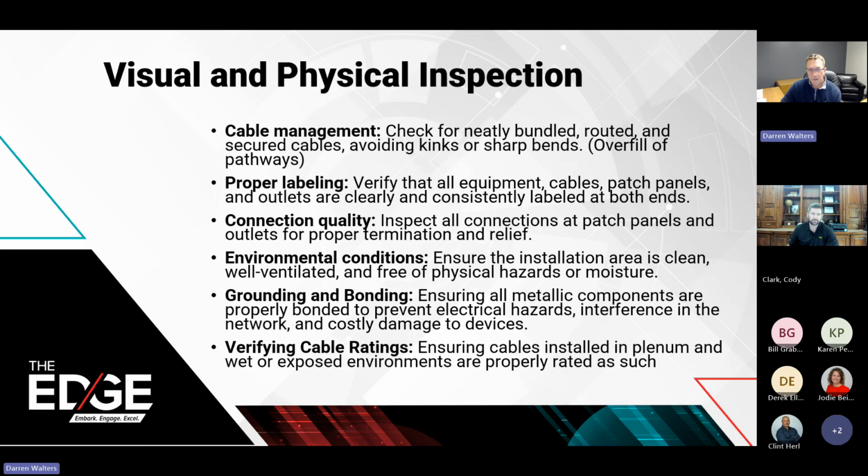Yeah, and one thing that we do just to add into that, because we hear about either plenum or non-plenum rated cable. Here at Nex-Tech, we try just to use plenum rated cabling all the time. It does a couple things for us. Number one, if we're talking about Cat 6, it allows us to stock one box of cable. We don't have to have two different or three different versions of it.